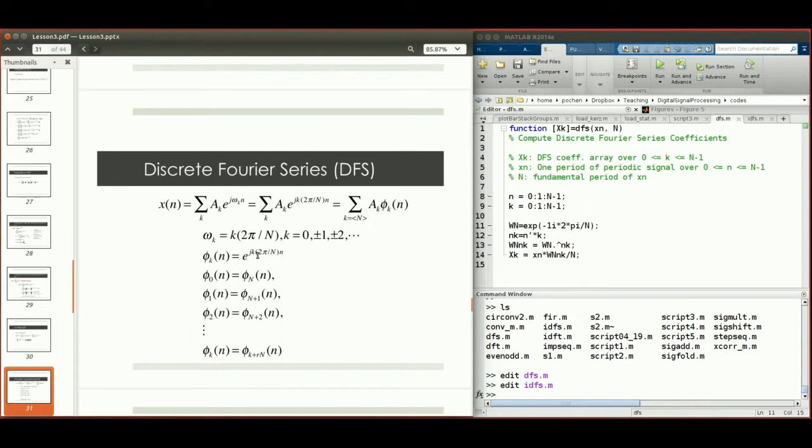And you have a term that's e to the j times 2 pi times n. That's one of the terms, right? Again, it's a complex number with a phase angle equal to 2 pi times an integer, so it's 1, right? And then you multiply with what? Don't forget k equals big N plus 1, right? So 1 multiplied by 2 pi divided by big N times n happens to be exactly equal to phi 1n.